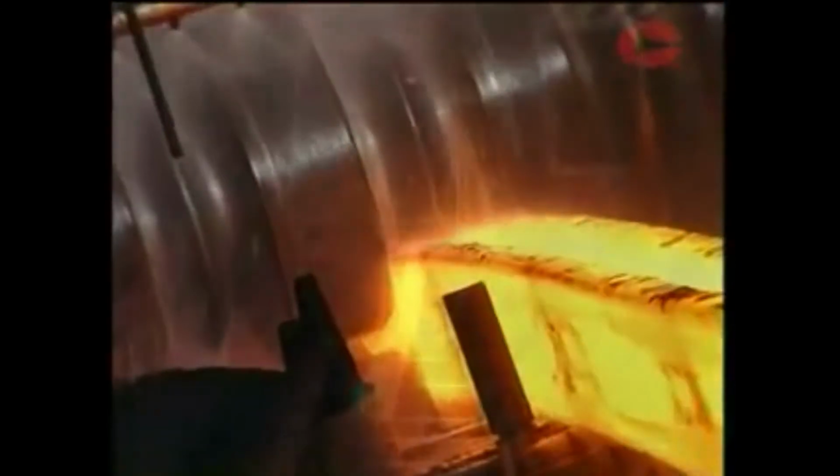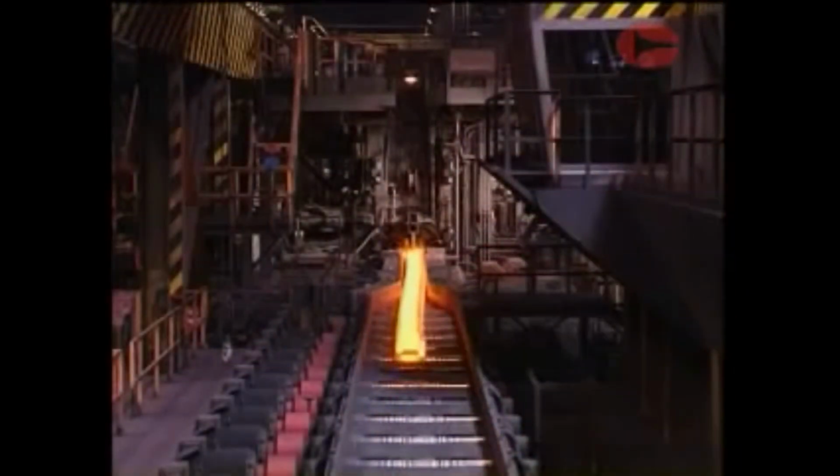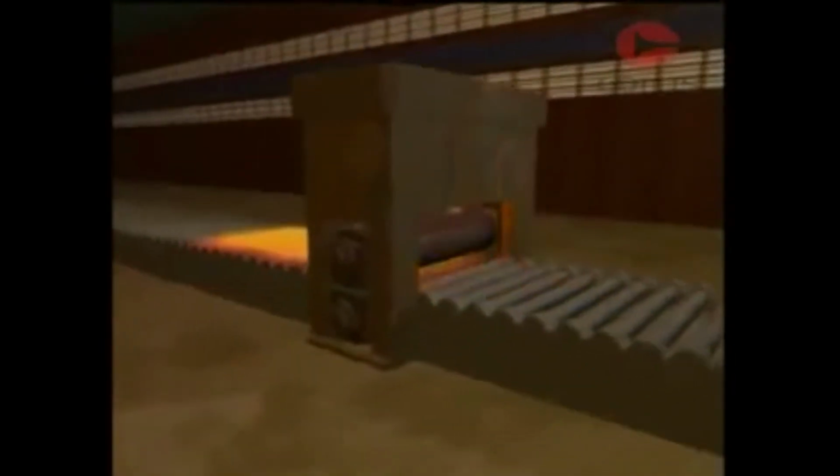The mill rolls themselves can either be plain for flat products such as strip, used for products such as cladding, or profiled for sections, beams and columns for use in construction. Mill stands have various roll arrangements depending on the product being rolled. The simplest arrangement is a two-high stand, used mainly for long products such as sections.